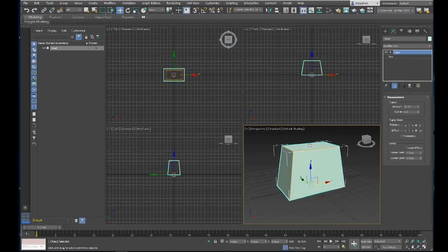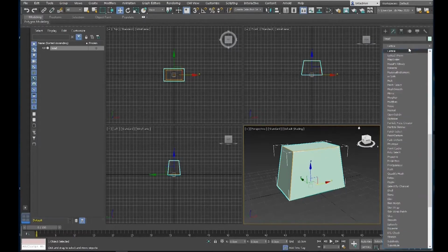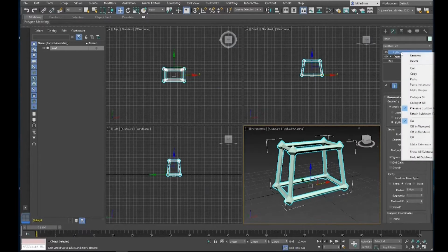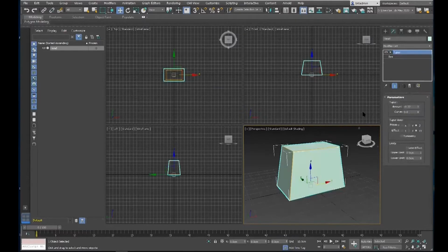But here comes the problem, because that modifier will remove some of the items. So let me quickly show this. If I choose a lattice, it converts my model. It's great, but the head is disappearing. Okay, so what should I do? I will just right click and remove this lattice. If you applied the lattice yourself, please select, right click and delete just the modifier. Okay, this is not deleting the whole model. This is a right click delete on the modifier and removing just the modifier.